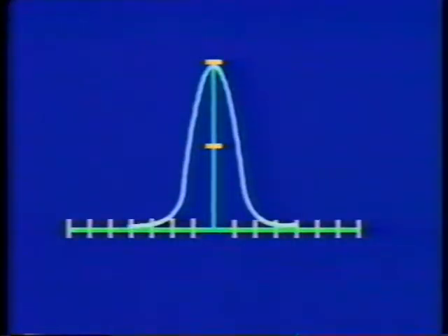Data problems fall into three categories: measurement uncertainty, unrepresentative observations, and spurious measurements. Measurement uncertainty is associated with the statistical randomness inherent in every measurement. Assuming that the instrument provides unbiased measurements, that is, no systematic error, the method of sampling and the precision of the instrument determine the size of the random error. For a well-designed instrument, this random error is small and is distributed about the correct value in a bell-shaped curve.